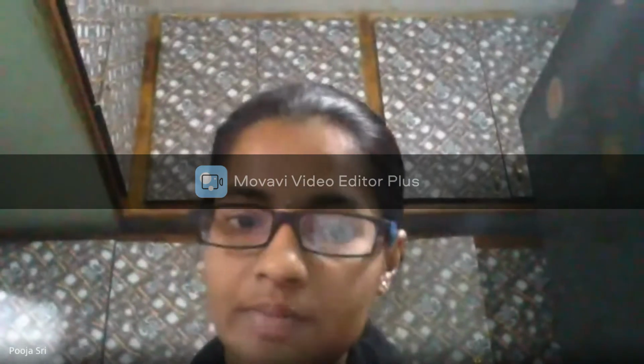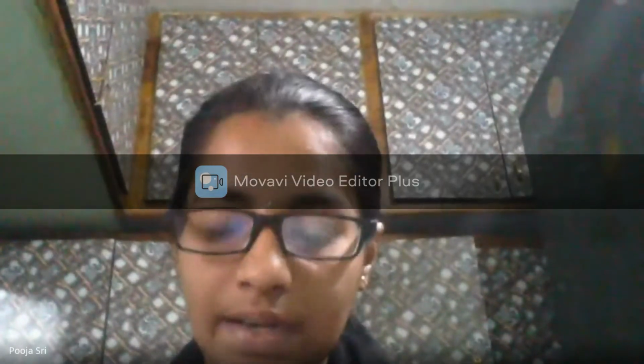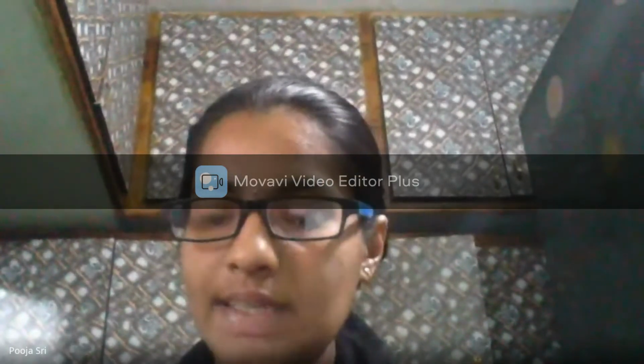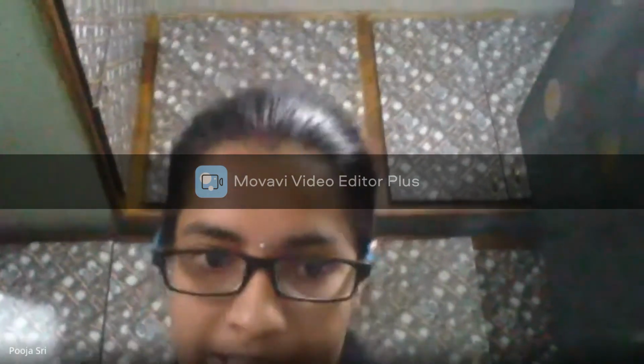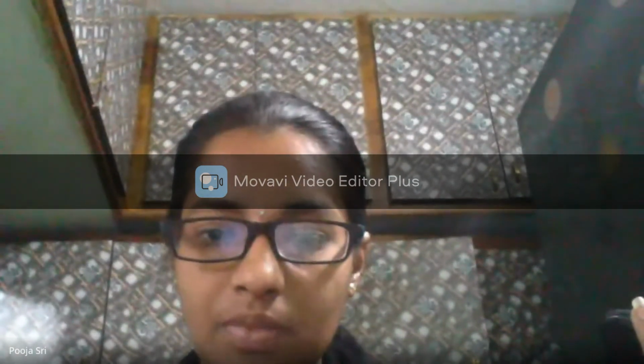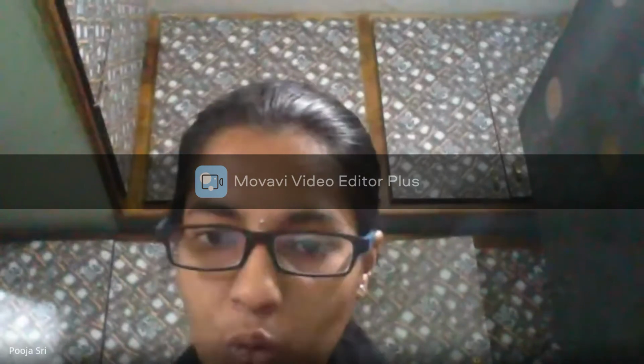Next, regulator. It is a device which provides a constant output voltage with varying input voltage. There are 2 types of regulators: one is the fixed regulator and the other is the adjustable regulator. We have used a fixed regulator, LM78XX. The last two digits signify the output voltage. Next is the Wi-Fi modem.